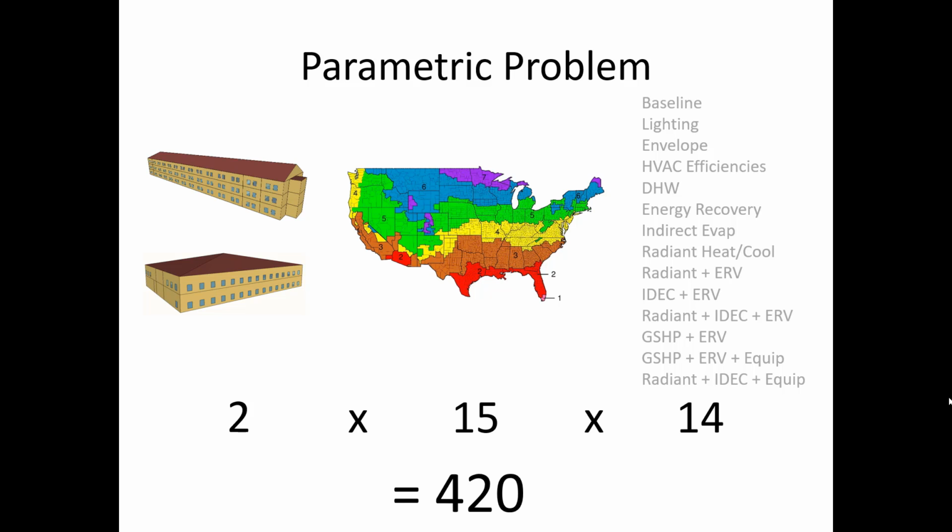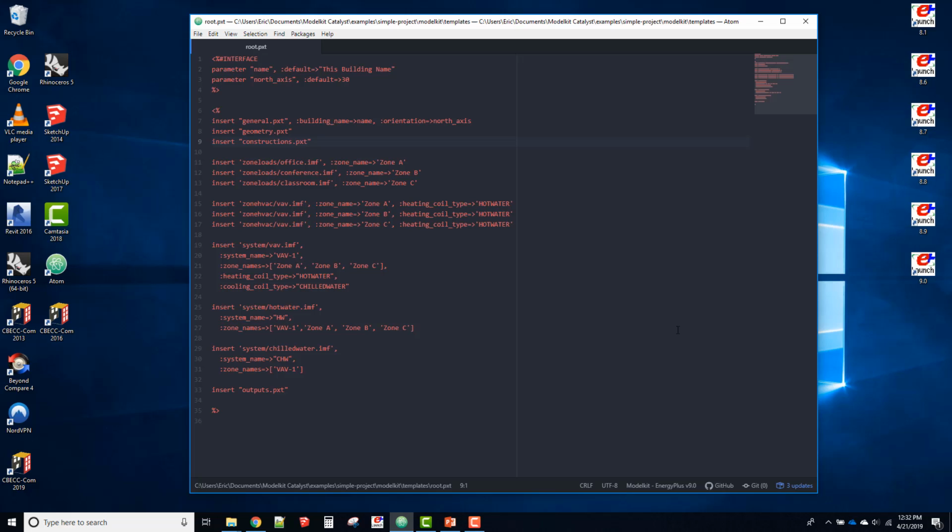Within the model itself, this just comes down to varying the design day parameters, and then of course when you run the simulation you have to point it to the correct weather file associated with that, with our root file that we've created over the last several videos, and we're going to vary it over the 15 different California climate zones.